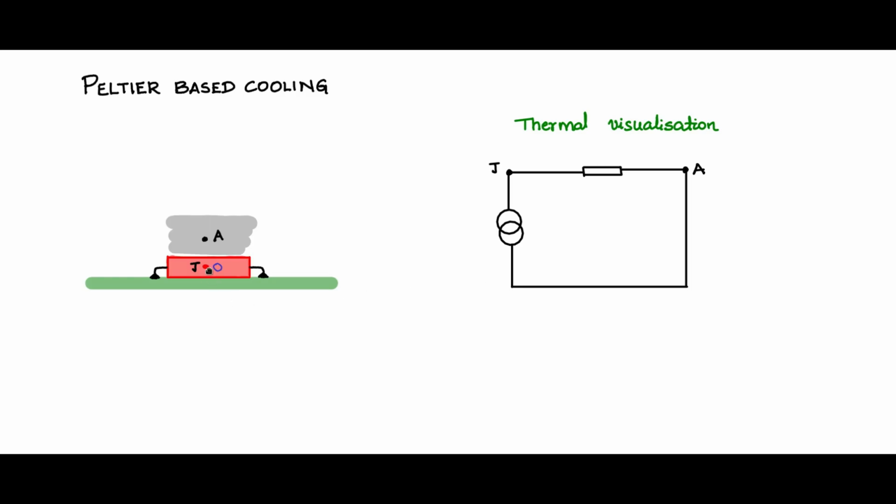And coming back to this physical picture visualization, this junction here is generating QC amount of power which is flowing out, as shown, and it is equivalent to having a current source here which is having a value QC, and that QC current source is flowing in this direction, and there is a drop across this thermal resistance, and that is the temperature difference between this and this.